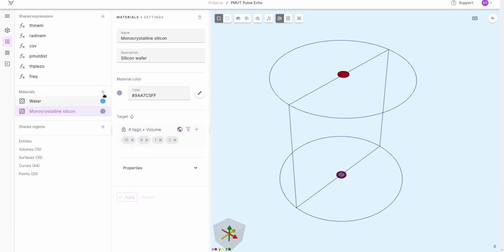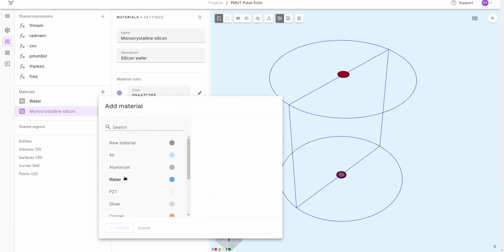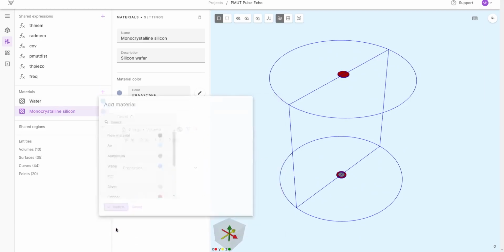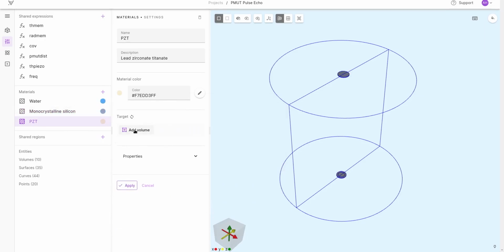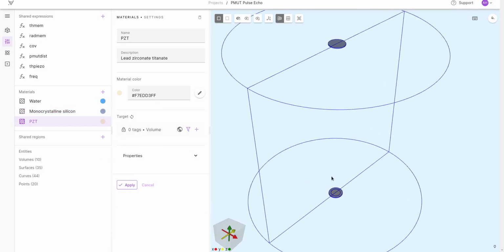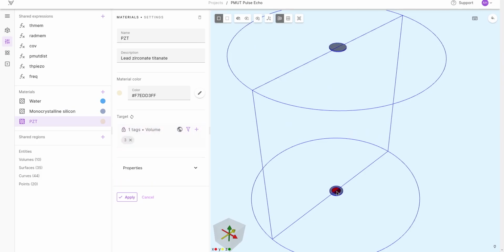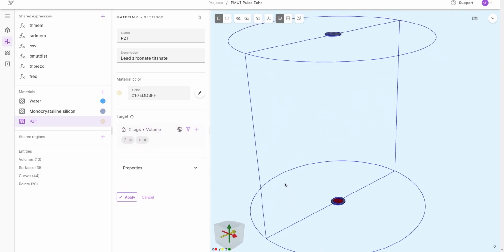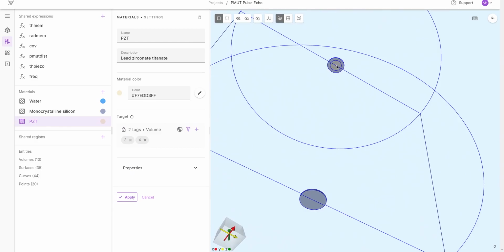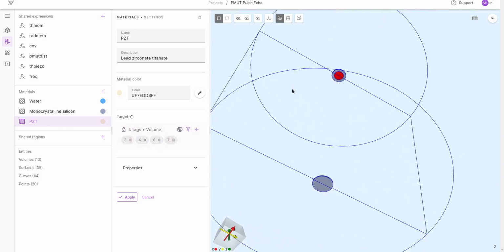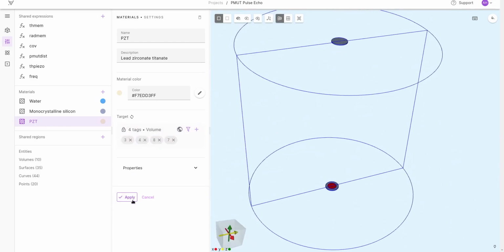And that's good. And then as a last step, we define our piezoelectric material, which here is taken as PZT. So for that, PZT is this thin layer on top of the membrane, covering 67% in radius for optimal drive. All right, so all the materials are defined.